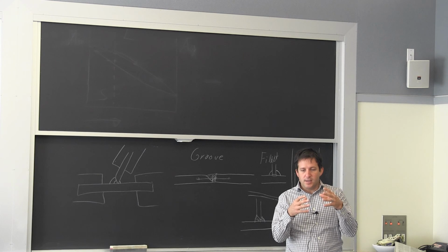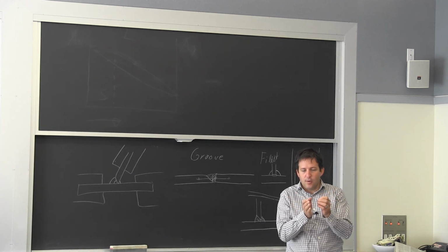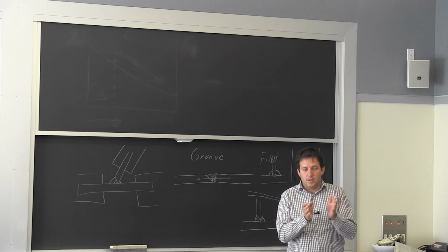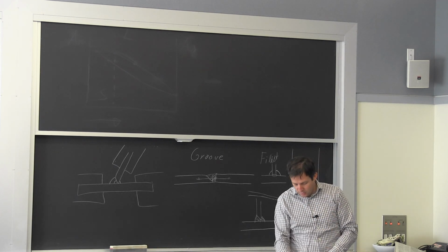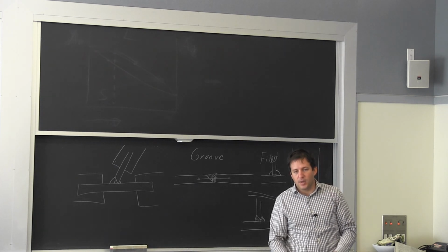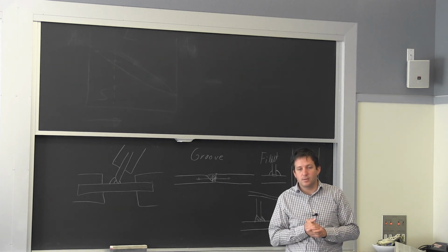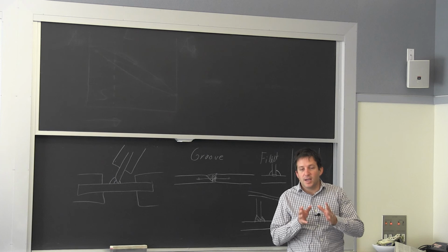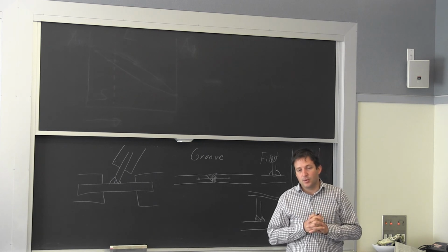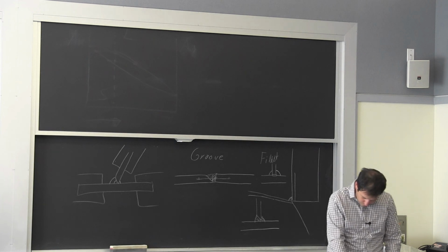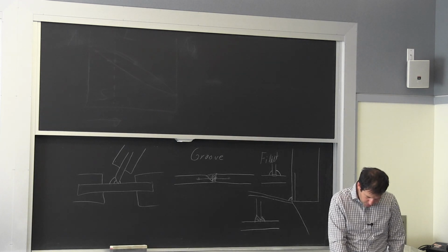Depending on how I heat it up is going to define how fine the separation is now of that martensite back into the ferrite and the cementite. So you're going back to the equilibrium phases, but it's going to be at a very, very fine scale, and therefore you still have strength. That's just a view of the martensite.